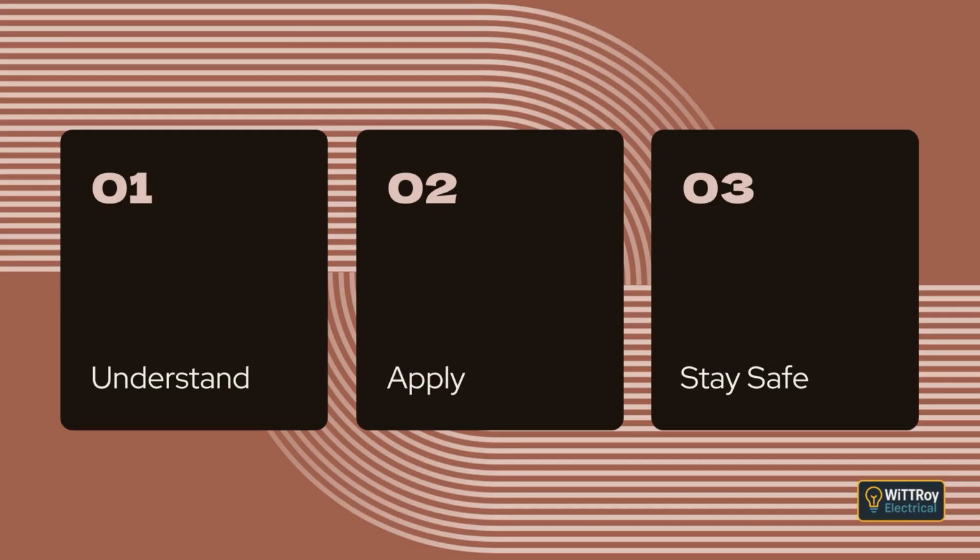Clause 2.9.4.6 Fuses. If the marking on a fuse holder does not match the actual fuse rating, the correct rating must be clearly marked at the fuse location. This could be on the fuse base, the enclosure, or the switchboard panel. When several identical fuses are used as a group, the rating only needs to be displayed once as long as they are side by side and all have the same rating.